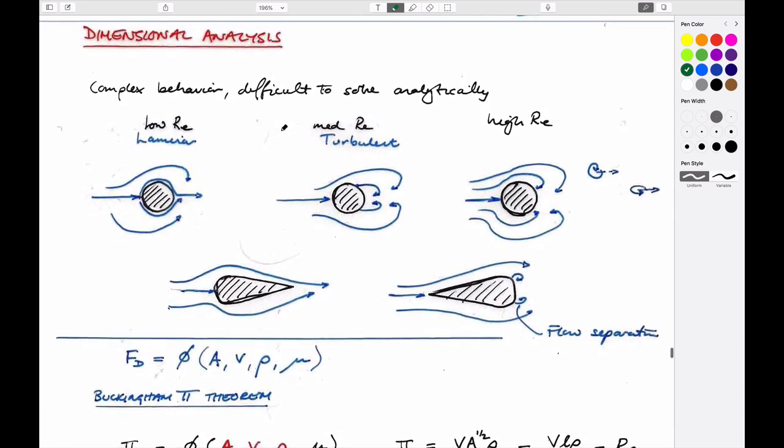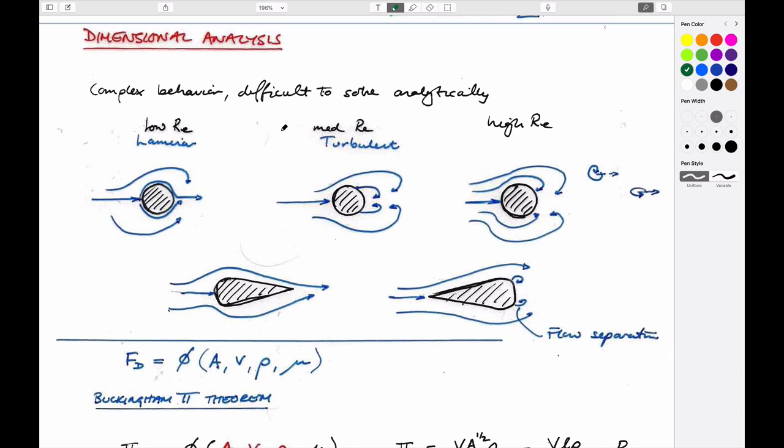The most important thing you saw in that picture of the airfoil is that as we change the viscosity, which is really a proxy for keeping the viscosity the same and changing the velocity, you get higher and higher Reynolds numbers in the same fluid. It just means you're increasing the velocity, because of the reciprocal dependence of those parameters.